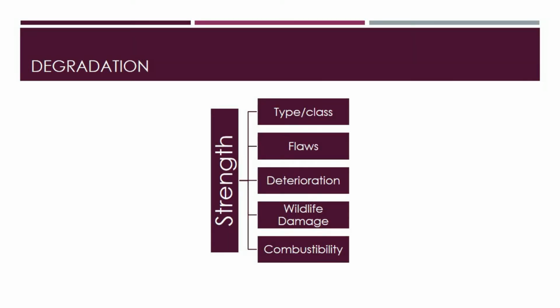Although most power companies now use fully treated wood poles, this was not always the case. Lines built 40 years ago or earlier may not have been built with fully treated poles, and instead may have used merely butt-treated poles. Fully treated poles are often considered to have a longer service life than butt-treated poles.